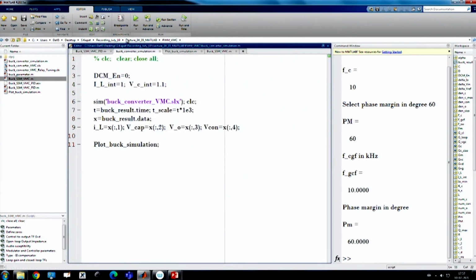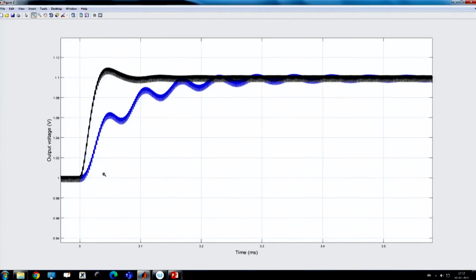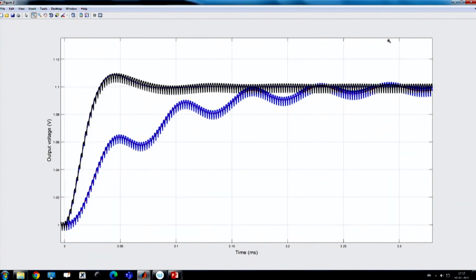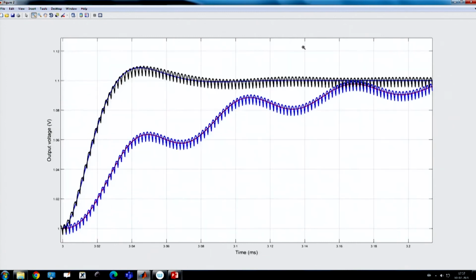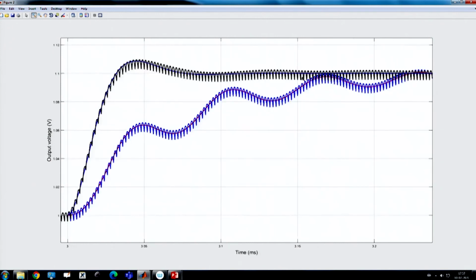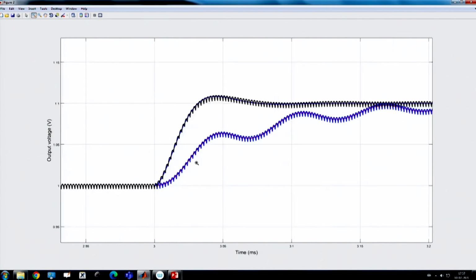Now we want to verify using our actual simulation. Okay. So this is a type 3 compensator now, and you see using type 3 compensator we can speed up the response significantly, because at the same operating condition the response can be drastically improved. You can achieve settling time even in 40 switching cycles, which we did in high load conditions. But in light load we can well damp the system, and this is the matching response of the small signal model and the actual switch simulation. So, this is the second case with the type 3 compensator. They are matching quite nicely, and you can really well damp the system by using this.